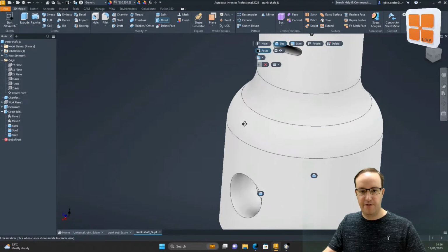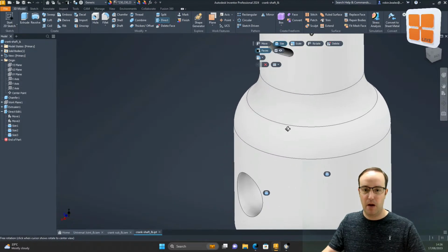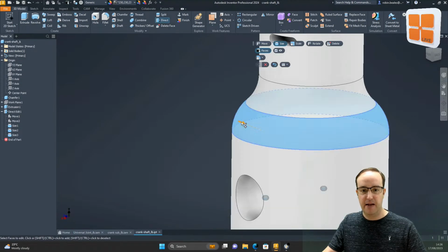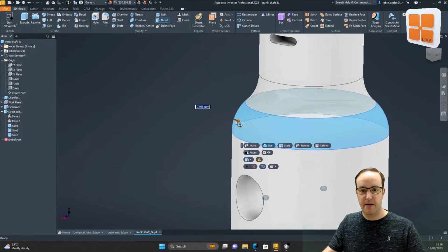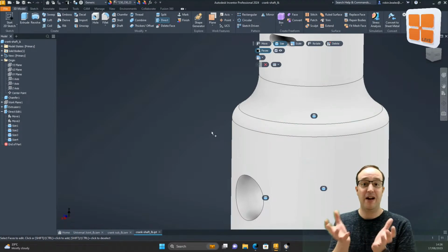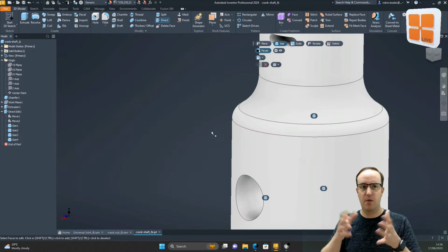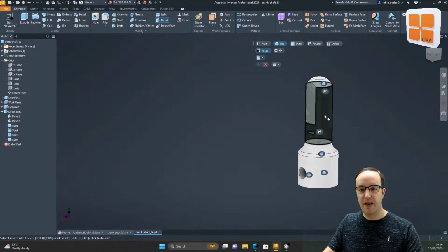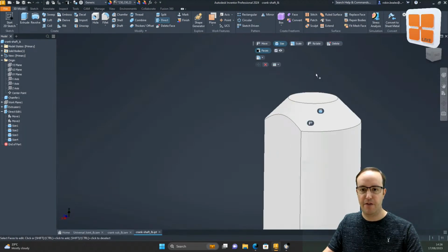And then maybe grab one of these fillets. That's more of a complex T-spline modeling procedure. I'm going to grab this large fillet and I'm going to edit it and make it different. So I'm just going to make it a little bit smaller here, like so. Obviously there are constraints that you're working within here. You've got to look at how you're modeling it. It won't let you do something that you can't do for obvious reasons. But we can come in and make changes on the fly.